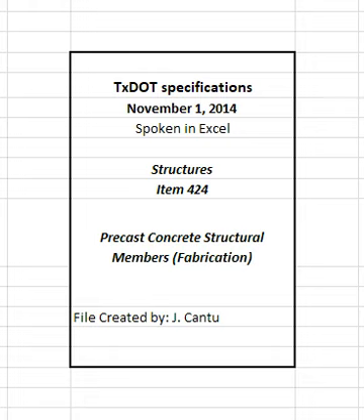Failure of individual wires in a 7-wire strand is acceptable if the total area of wire failure is not more than 2% of the total cross-sectional area of all strands in the member, and if no more than 1 wire fails in any single strand. Any setup with 1 or more broken wires must be examined by a licensed professional engineer or quality control supervisor, as defined in DMS 7300, Precast Concrete Fabrication Plants, to determine the cause before continuing stressing operations on the particular casting line.